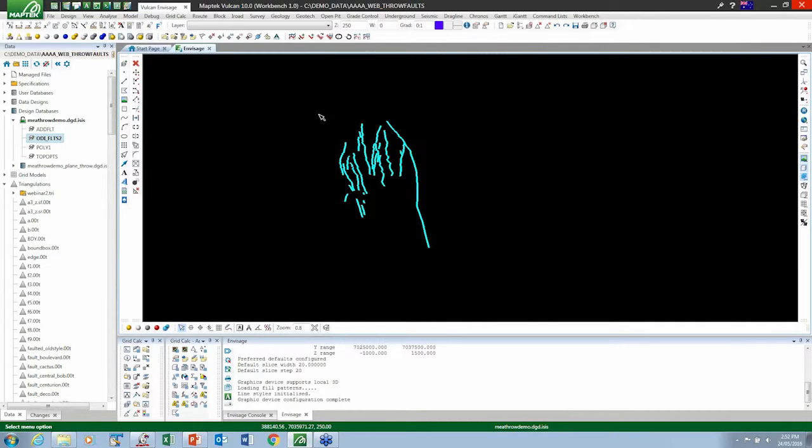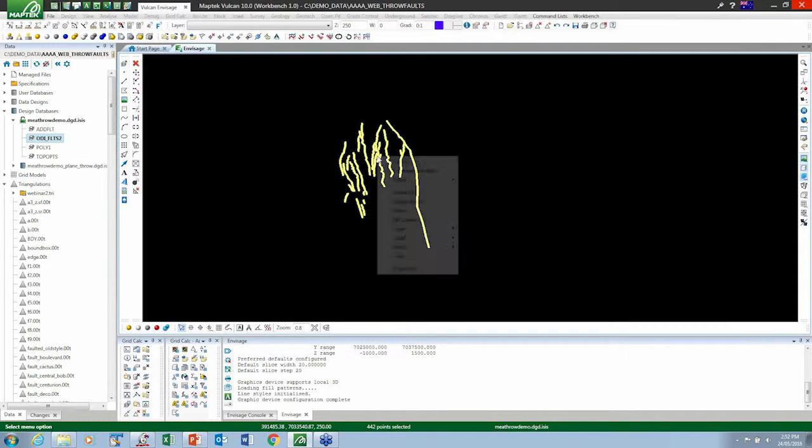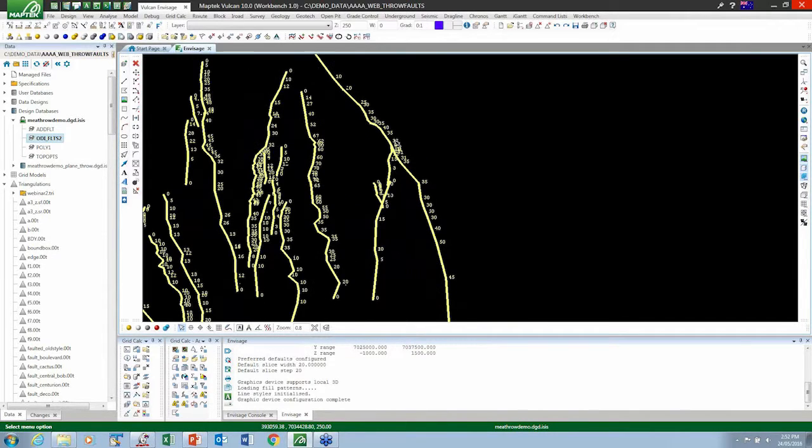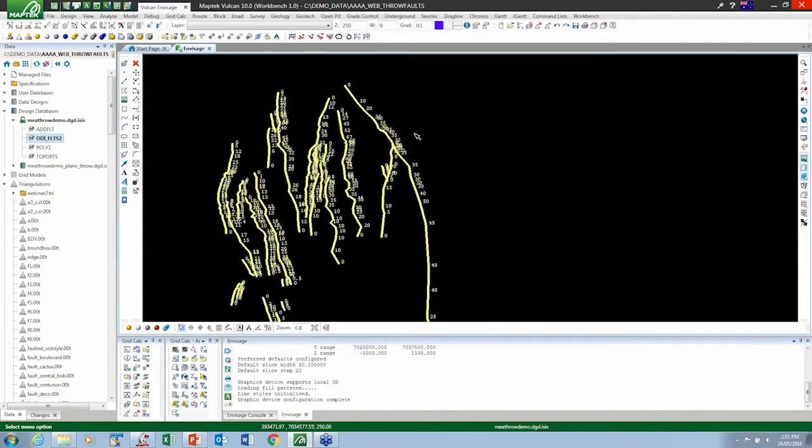And obviously you always could do that, way back to version 3 you could do that, whereby you could offset a grid vertically via a throw stored in the W tag. So we're still using that. So each one of these points has a throw. In this case it's in meters. It's tapering off to 0 at the ends, but it doesn't have to. And the sequence of the points, if I stand on the first point and look along it, it's going to throw up to the right if it's a positive value. So there's nothing new in that.